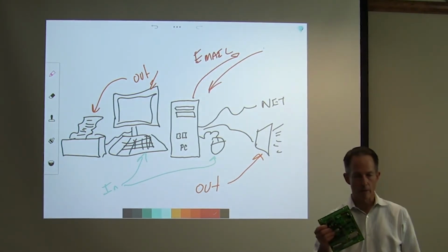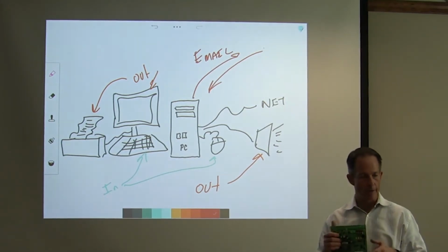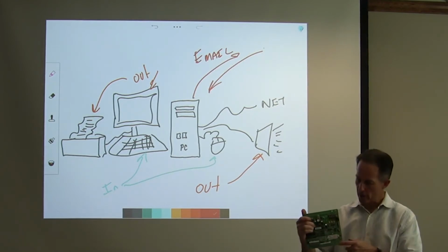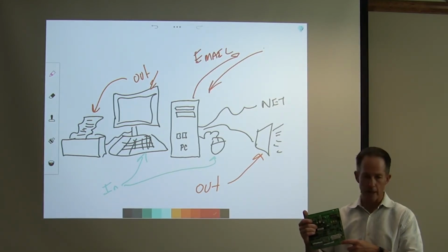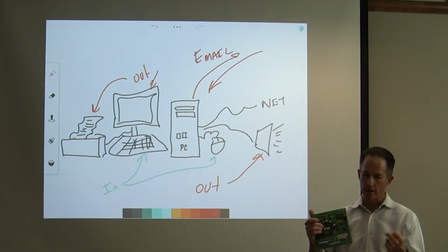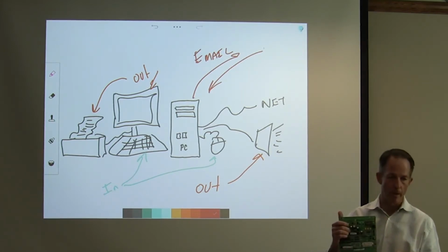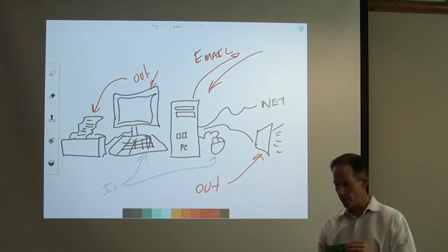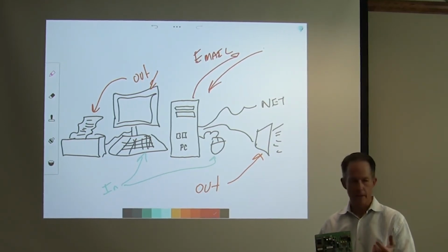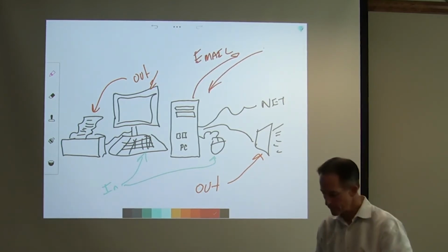We mentioned in our last version of this little training session that once in a while we'll get a card that will lock up for these. We call them a screamer. Essentially this output on the communication pulls down and holds, or goes so fast that it never lets the communication flutter up, and it pulls it to 0. Or there's times it may get shorted. And so we can troubleshoot that using a normal meter, because the communication rate is so slow, we can see those transitions.